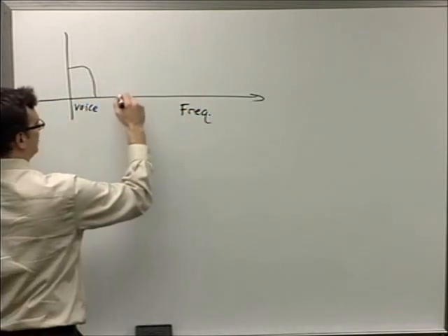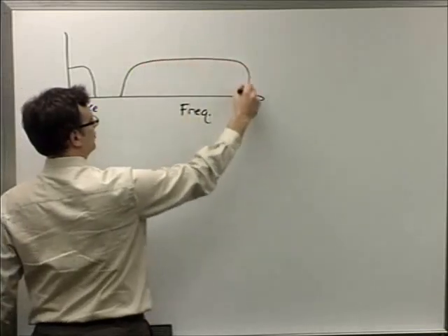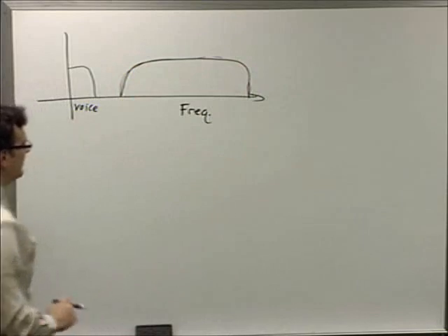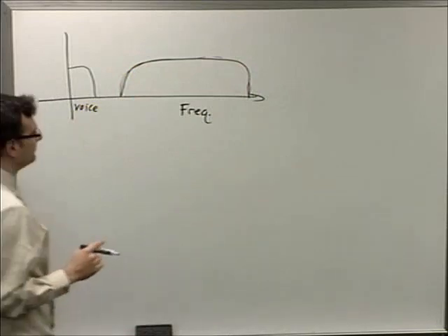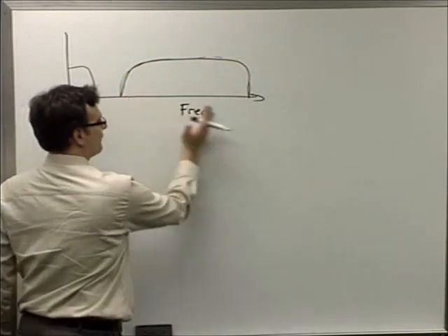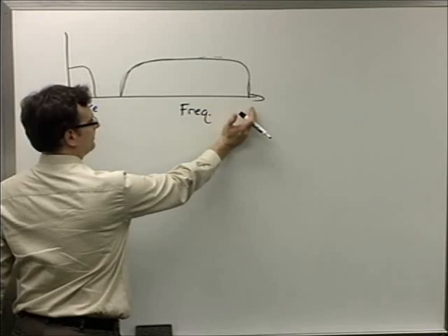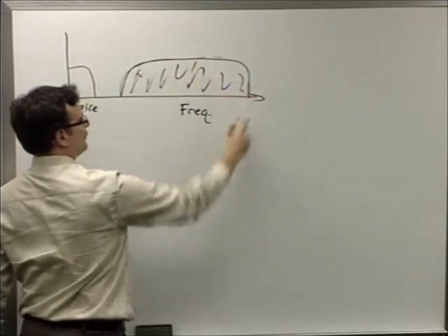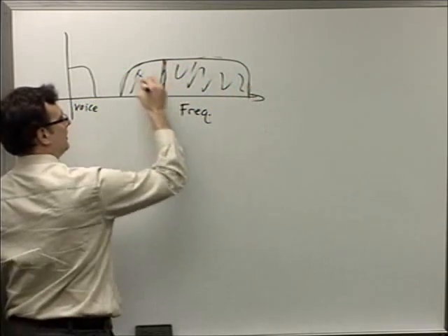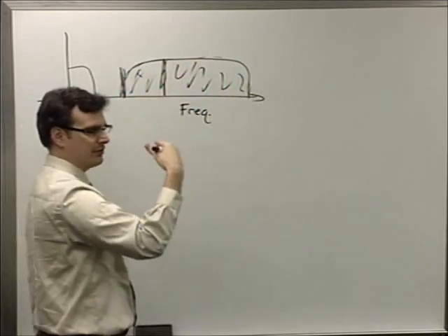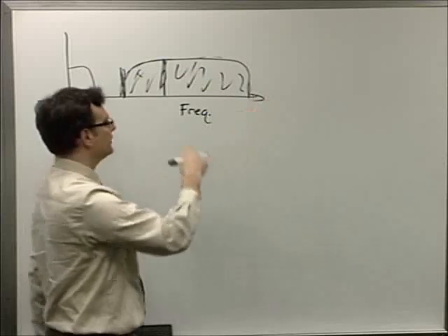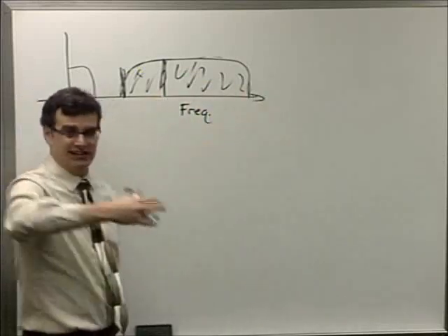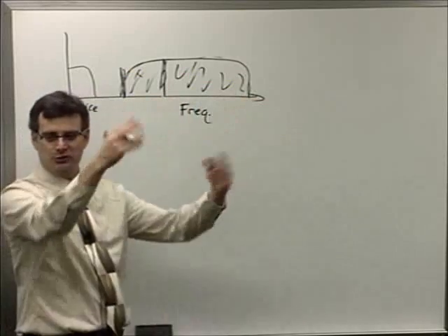And then there's a part up here that you don't listen to on your voice receiver. It'll go up to past a megahertz in some cases. But this is a lot of frequency. And this signal is used for data. Usually there's a downlink, uplink portion where you can send something from your computer up to the phone company here. And then a larger portion that's used for downlink, because you tend to consume a lot more data than you produce or send up, right?